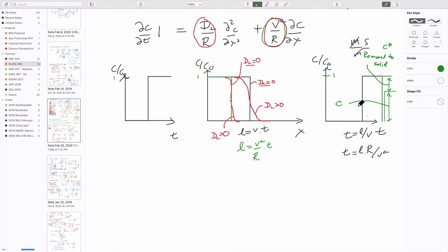And so you'd also expect that the breakthrough curves, although delayed, would become sharper as well. And not included in this equation, but what makes eminent sense is that if you're removing some to put it on the solid and it's taken out of the flowing fluid, there's less mass in the fluid, and so you'd expect the downstream concentrations to be attenuated.